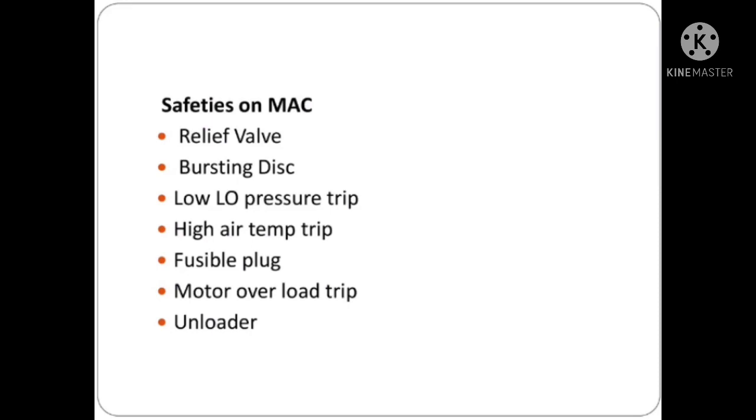Then comes the fusible plug. If the high air temperature trip doesn't come into action, then the fusible plug will. This fusible plug is made of a low alloy material which will melt at 105 degrees Celsius and will release the air to the atmosphere.